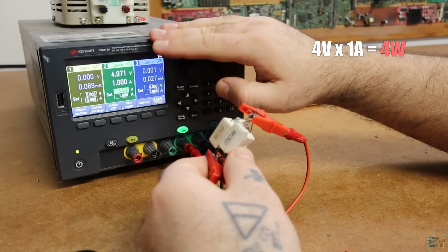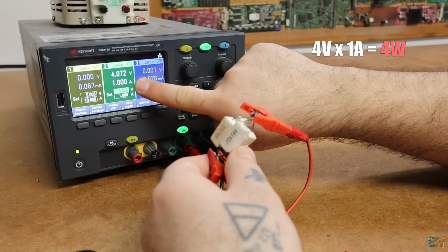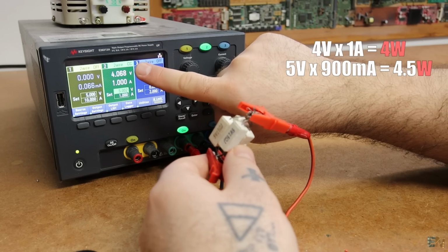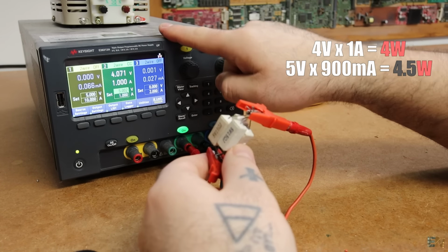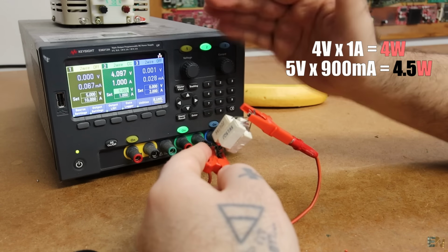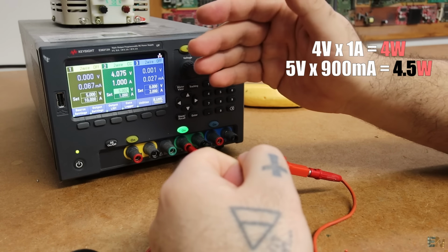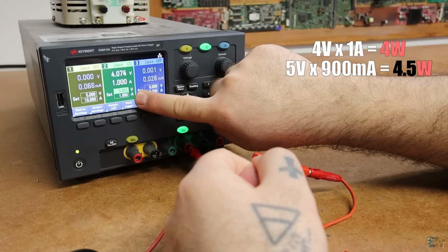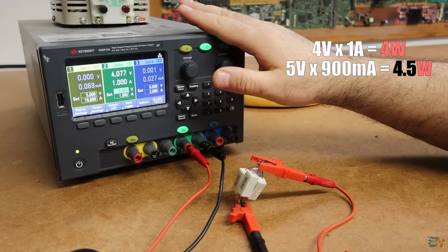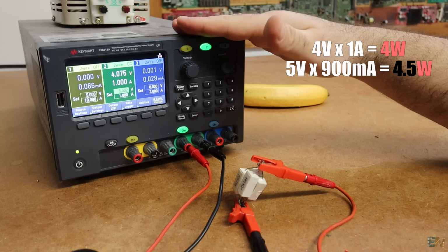But we can get even more than that just by lowering the current a little bit. For example, if the current were 900 milliamps and the voltage still 5 volts, we will have 5 volts multiplied by 900 milliamps, which is 4.5 watts. So as you can see, just by changing the current and the voltage, we can still increase the power. In this case, the power is limited to 4 watts, but we can get up to 4.5 watts just by lowering the current a little and still keeping the voltage at 5 volts. I hope that's understandable, and that's what an MPPT controller will do. And now I can explain how it works and how it does that process.